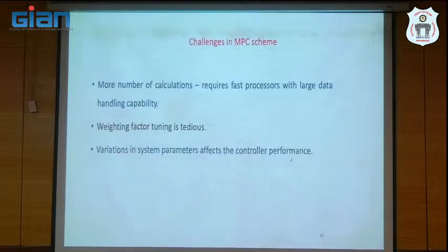So what are the challenges in the MPC method? What is the main issue? The number of calculations is more. That's why nowadays a lot of research is going on to minimize parameter sensitivity in the prediction. To predict the torque profile or flux profile, a lot of machine equations are required.